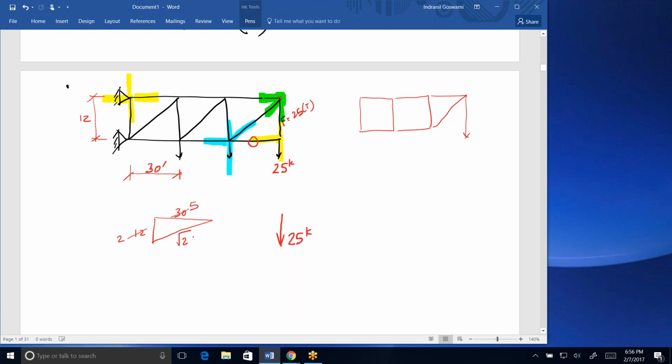That means this will be square root of 29, right? 5 squared plus 2 squared is 29, square root of 29. Which means that my forces are also going to be in the same proportion. So if the vertical proportion is 2 and the horizontal proportion is 5, that's a factor of 2.5. That means if the vertical is 25, this will be 5 over 2, 2.5 times 25, or 62.5. You can say that just by inspection without writing down equations. And therefore, by necessity, this force will have to be one coming in, because you notice that these two push inwards, tensile, and the compressive effect on the member has to keep it in equilibrium. And this must be square root of 29 over 2 multiplied by 25, whatever that is. I can't do that in my head.